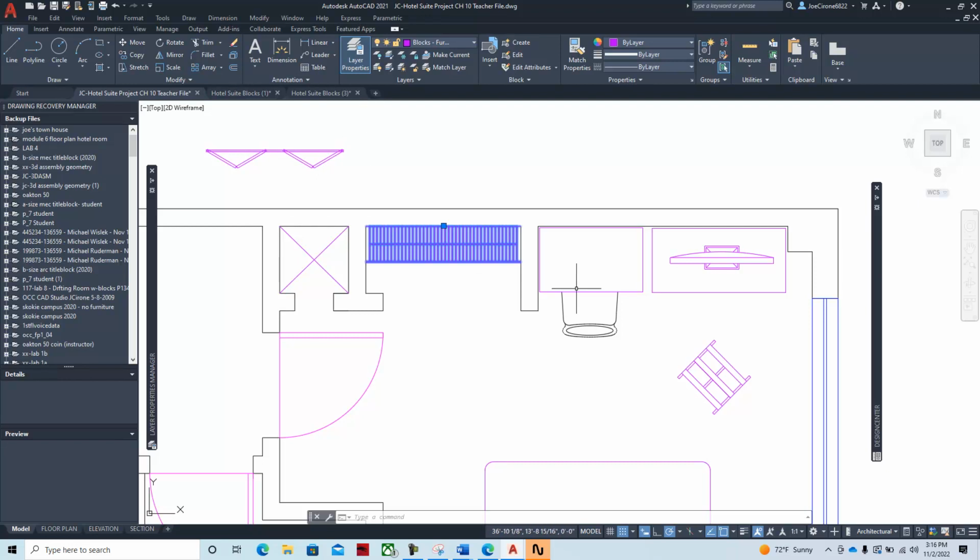To add the bifold doors, what we'll do is we'll create a line for construction and then move this from the midpoint to the midpoint. And if we want to erase that, we can select them both and then hold Shift and remove one of the geometries. And that's a trick to get rid of line on top of line geometry.